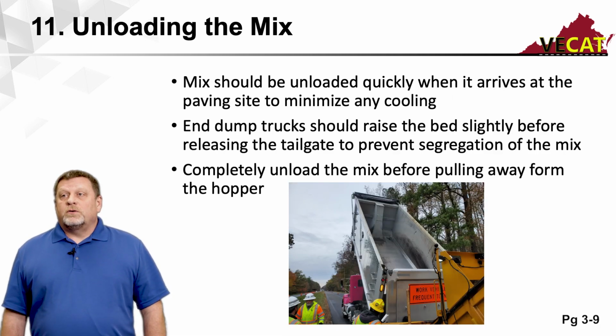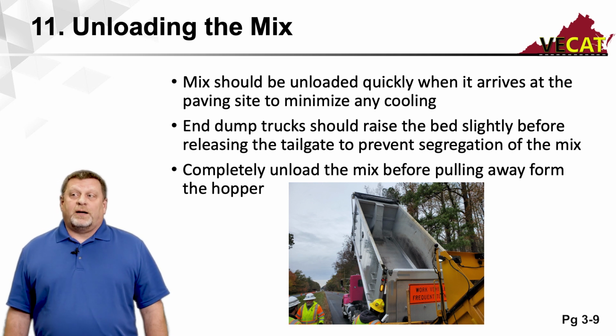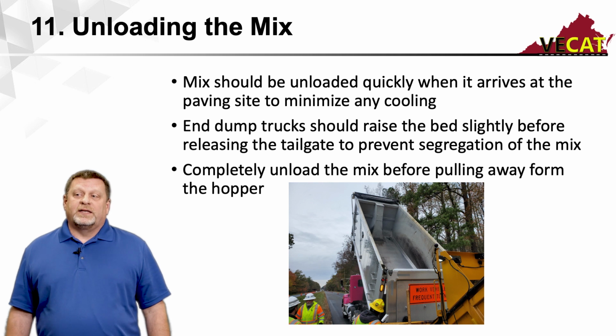Now we're going to unload the mix. The mix should be unloaded quickly when it arrives to the job site. Again, we don't want to have any cooling. In dumps, we typically will raise their beds slightly. We talked about this before they release their tailgate.